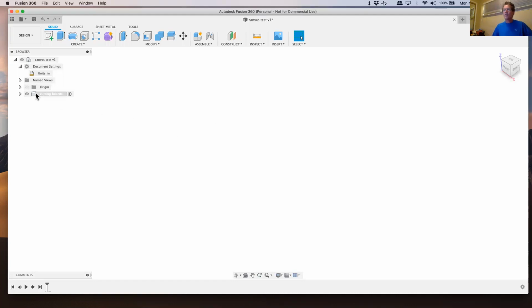Now, when you create components, you can create all the components that you can think of up front, and you can also use a structure of sub-assemblies if it's relevant. For example, if I were modeling the Ortur laser, I would have a sub-assembly for the laser assembly itself, one for the X-axis module, one for the Y-axis module, and then the subcomponents within that sub-assembly.